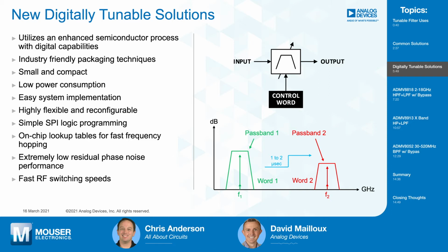They employ simple SPI logic programming, and some of the digital functionality that we have is lookup tables on the chip for fast frequency hopping. And we'll get more into what we refer to as SPI fast latch mode in the device. The residual noise is excellent as well, and the tuning speed is great.